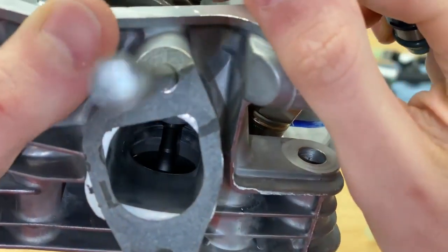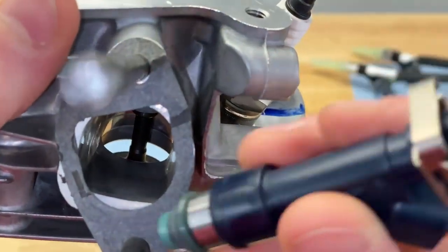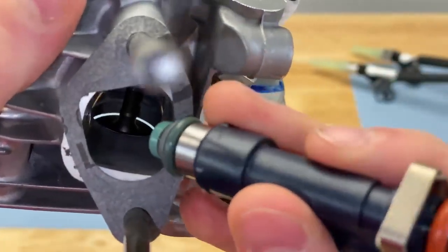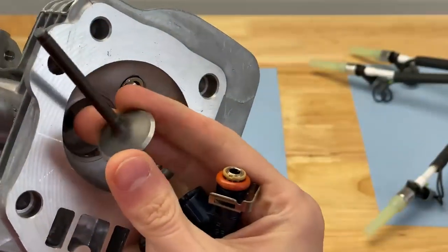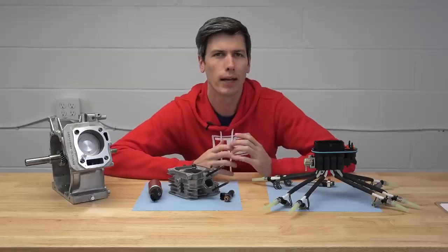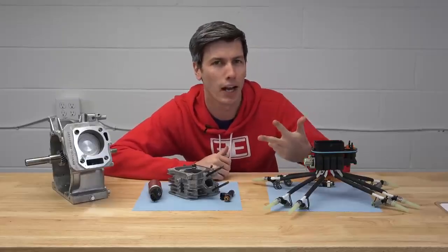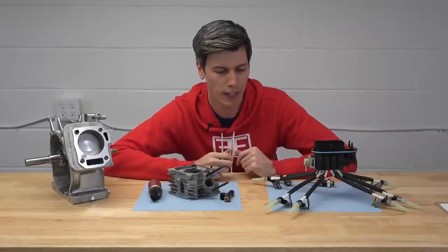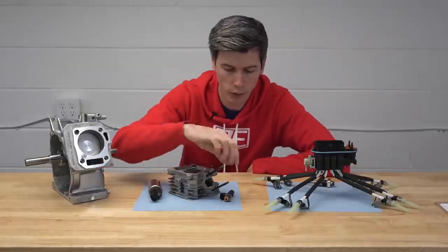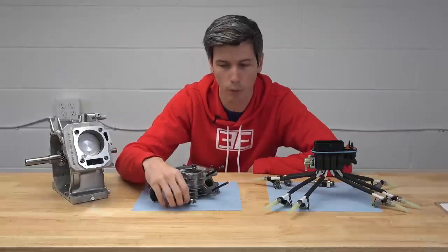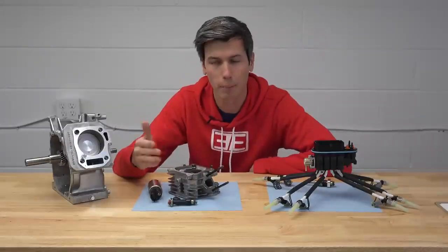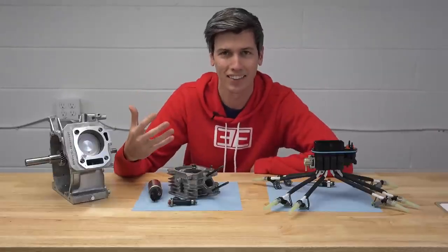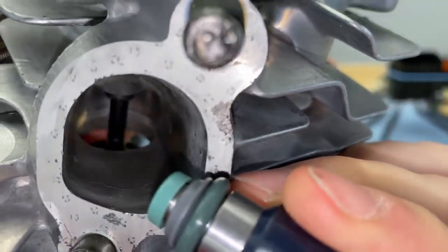Another advantage of port fuel injection versus direct injection is that the fuel can help clean your intake valves. Gasoline will have additives in it to help remove and help prevent carbon deposits so that as fuel is sprayed in the manifold, some of it will hit the intake valves and help keep them clean. So versus direct injection, packaging, cost, and the amount of time that the air and fuel has to mix are all advantages. However, going back to air-fuel ratios, because that fuel is sprayed into the intake port, some of that fuel ends up on the walls, and that can actually influence your air-fuel ratios depending on the scenario. So it's something that has to be taken into consideration, and it's a bit of a disadvantage versus direct injection.